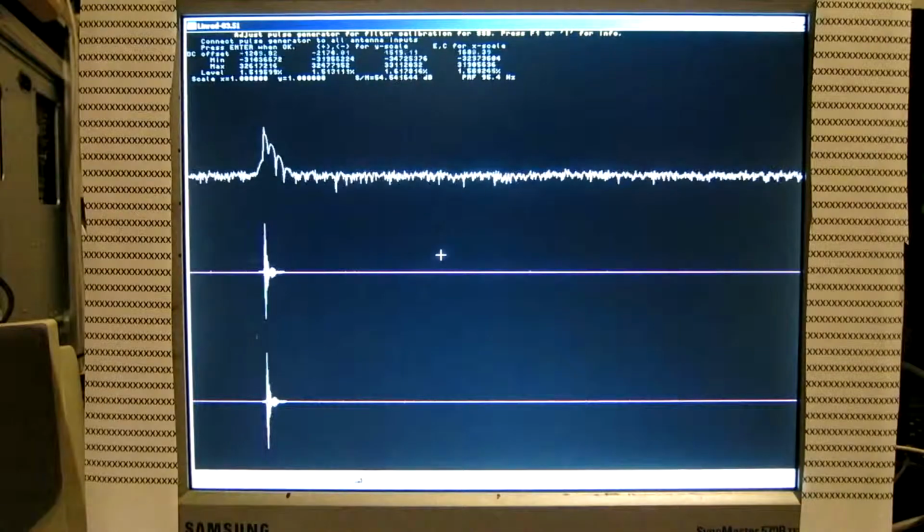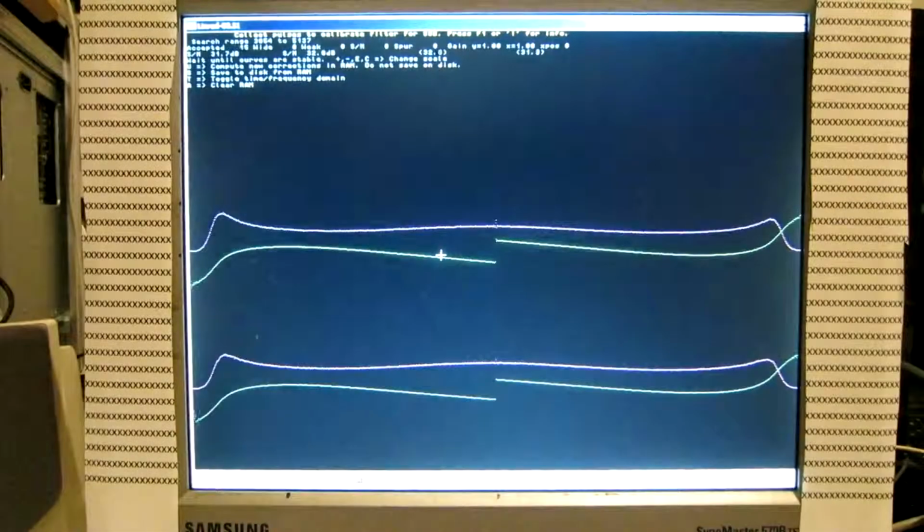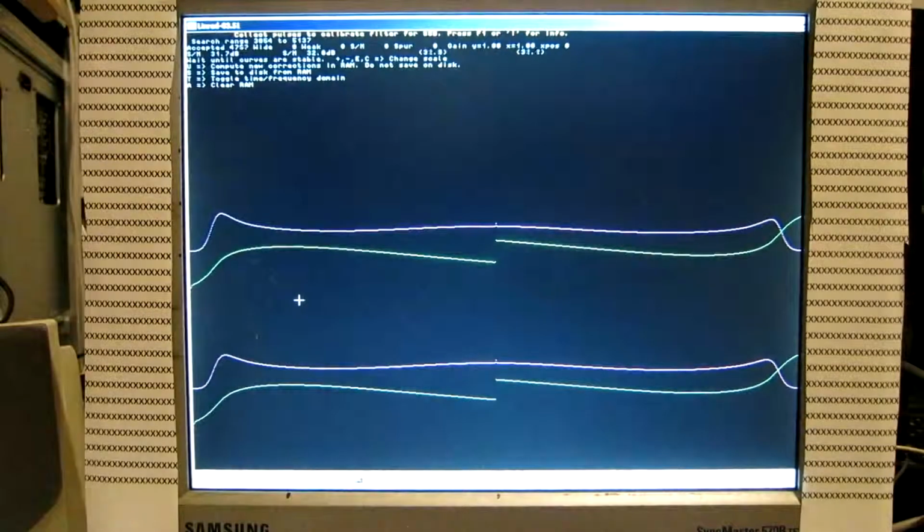So let's try enter. And now Linrad is collecting the average of the amplitude, that's magenta, and the average of the second derivative of the phase, and that is green. And I wait for a while to allow very good statistics. Now it is nearly 5,000 pulses. That is more or less overkill.